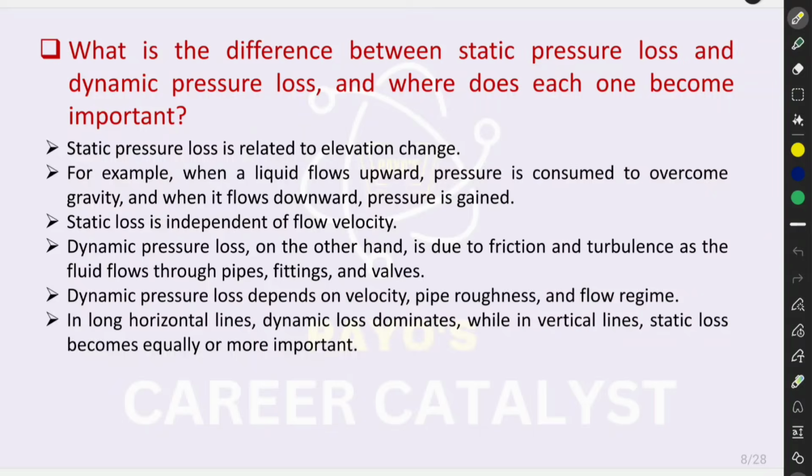What is the difference between static pressure loss and dynamic pressure loss? And where does each one become important? Static pressure loss is related to elevation change. For example, when a liquid flows upward, pressure is consumed to overcome gravity, and when it flows downward, pressure is gained. Static loss is independent of flow velocity.